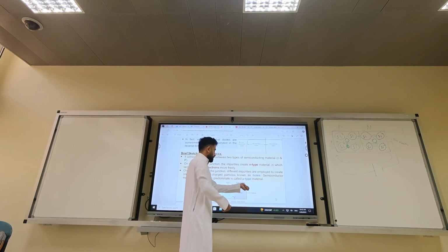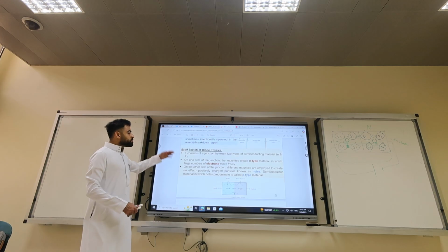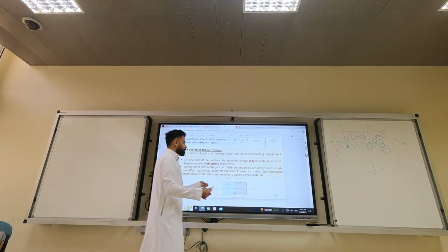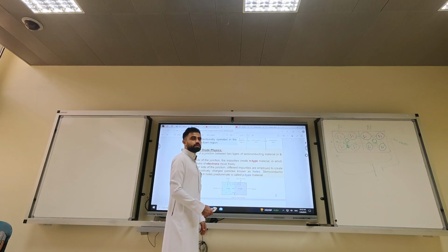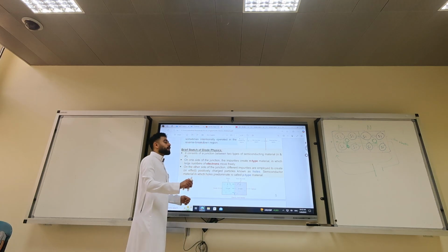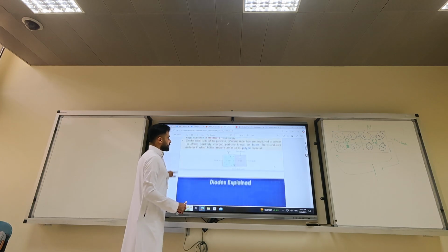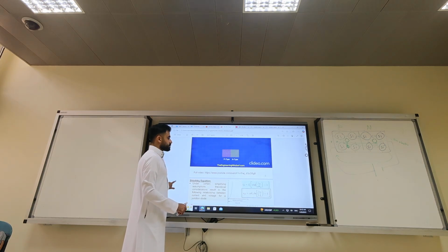If you put the positive here and the negative here, it will be minus 0.7 DC. Okay? Once you add the impurities and you apply a sufficiently large voltage, more than 0.7, electrons will be moving in your circuit. If you reverse the direction of the voltage, it will block the electrons from moving, unless you apply a relatively large voltage, then it will break down. And this is the video that we talked about. Okay?